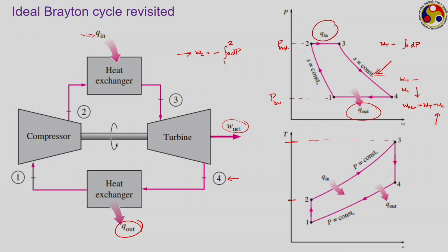And correspondingly, the Brayton cycle leads to the ideal cycle for vapor based power generation, which is called the Rankine cycle, named after William Rankine. The Rankine cycle can be viewed as just the phase change version of the Brayton cycle, where we still have two isentropic processes and two isobaric processes. However, instead of working always with a gaseous medium, we shall be working with a phase change medium, so that the expansion part is done with a gaseous substance, the compression part is done with the liquid phase of the same substance, and both heat addition and heat rejection at constant pressures will be associated with phase change.